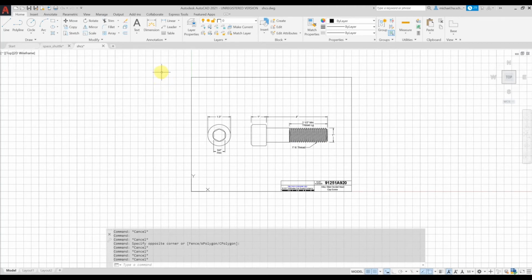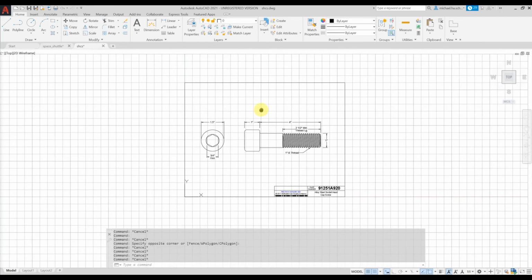So next we're going to talk about line weight. It's an important topic, especially when you print. You want the edges of the objects to have the right thickness, as well as other line types to have the standard thickness. In order to do that, on this drawing that I've imported from a PDF file, let's say I want to highlight the drawing by displaying the line weight.